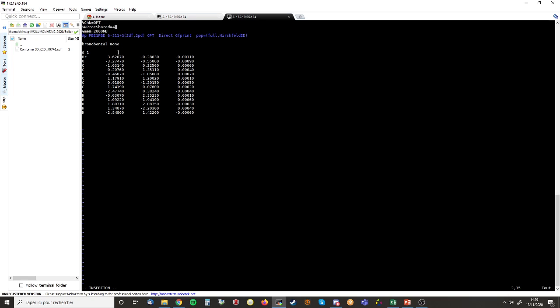I can do more, but for example, if I use 8, the calculation will not go twice as fast, because when one processor is calculating, sometimes it is waiting for the answer of another processor, so there is waiting time. And Gaussian is not really super efficient. If you put 20, it will not be 5 times faster, it will be like 3 times faster.